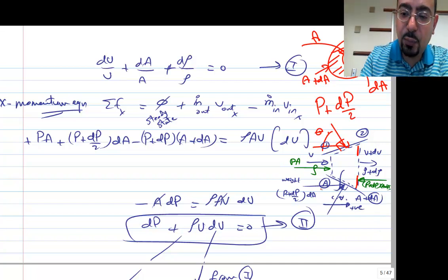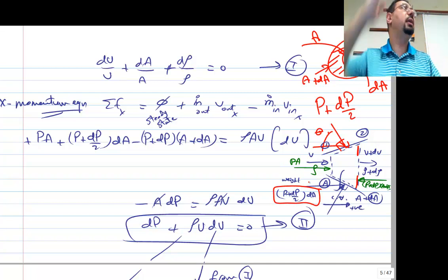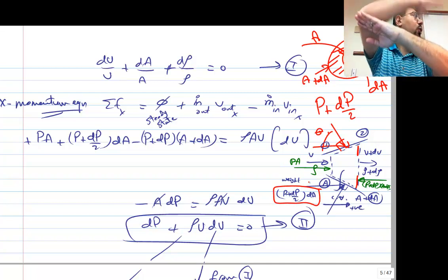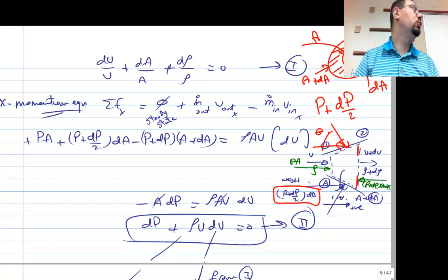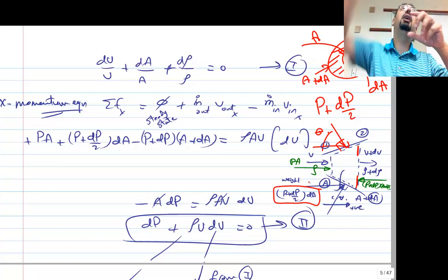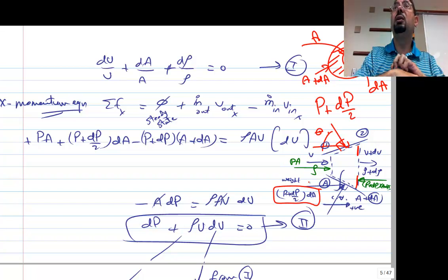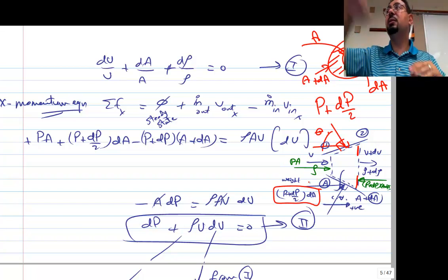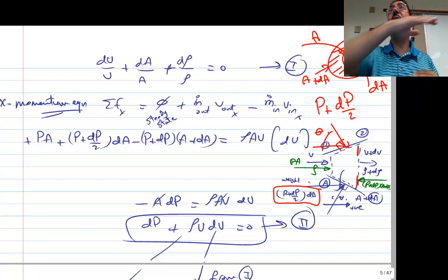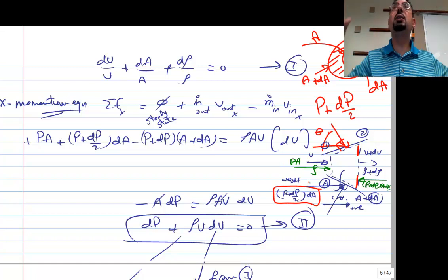So that's why this force, P plus dP over 2 multiplied by dA, is the horizontal component of the pressure on the wall. So rather than saying the whole pressure multiplied by this area and then take cosine of this angle, remember from hydrostatics in fluid 1, when you had those curved gates, and we wanted to calculate what's the F horizontal and what's F vertical. The F horizontal was, let's multiply the pressure on the gate times the projected area. That's what we are doing over here.